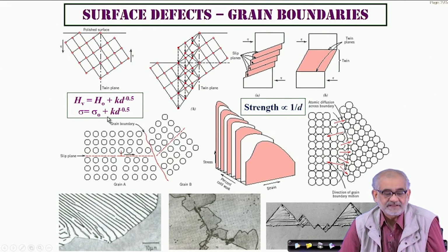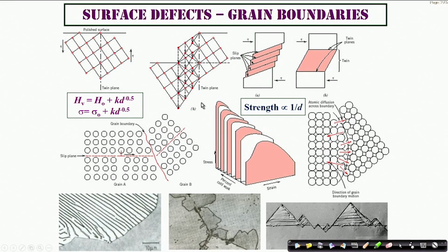So either way, this mechanical strength increases as the size of the crystallite, or so-called grain size, decreases. And this is the famous Hall-Petch relationship, which many of you probably already know, which simply says that the smaller the grain size, the greater the strength of the material, and that strengthening arises purely because of the barrier posed by these boundaries to dislocation movement.